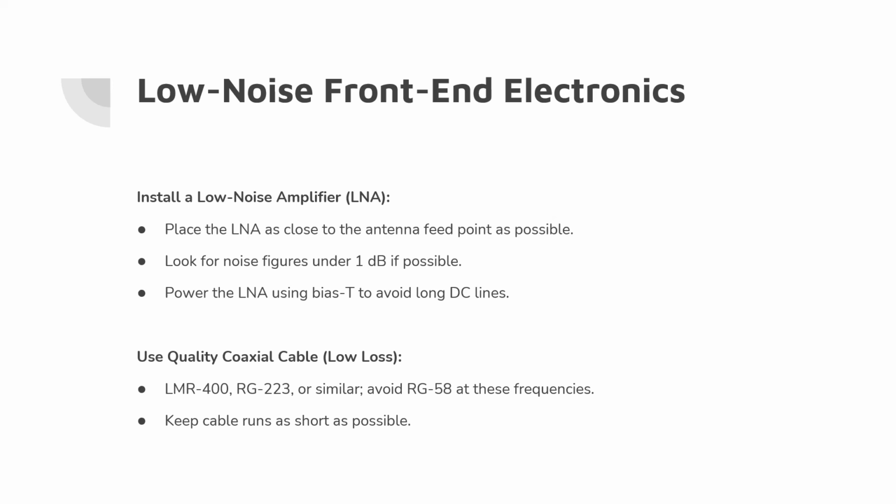You could then add another small gain amplifier at your LNA if you think you're having losses on your coax run. I know for that back dish that I'd kind of like to convert over for the hydrogen work, I also have a long run. It's all the way from the back of my yard property to inside the house, and I buried it inside PVC tubing from the dish. The coax from the LNB at the dish goes right into some PVC tubing at the concrete base, and then that was underground all the way to my home.